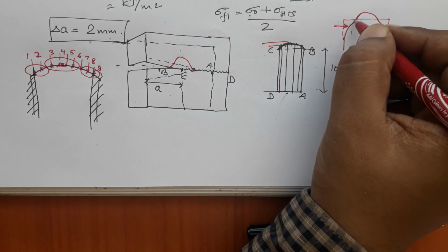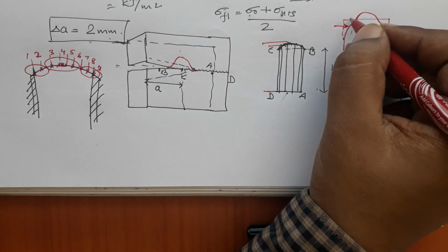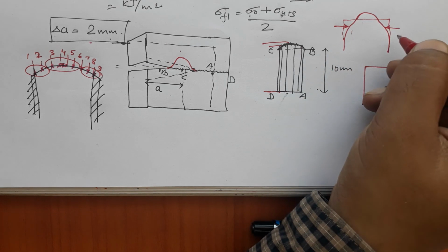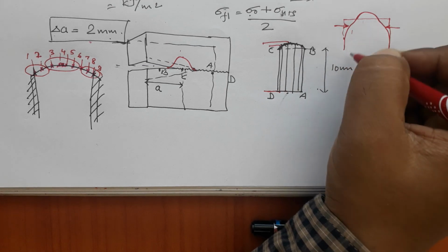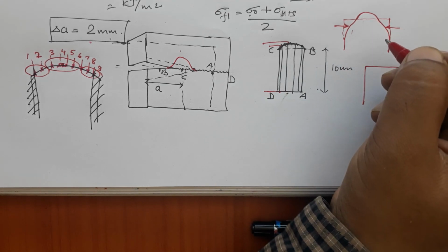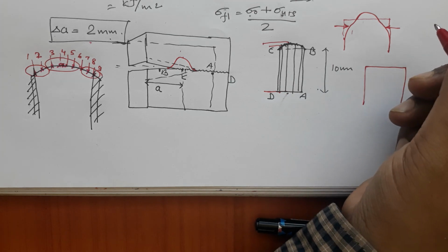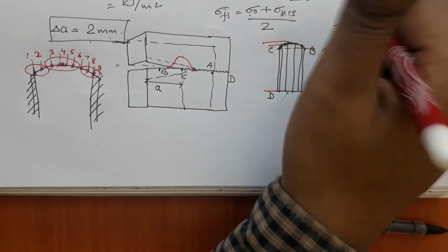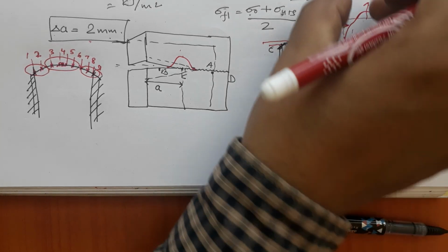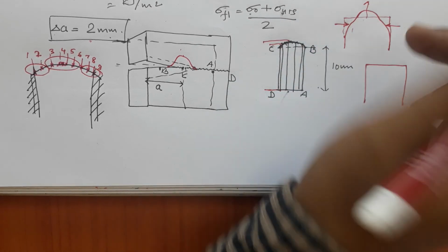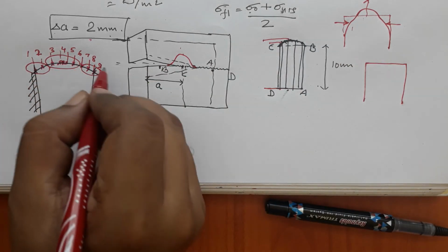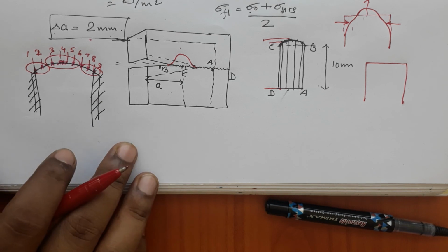So, what has happened is the material has sunk in from the sides. Why has that happened? Because the surface is relatively free in comparison to the center. The center is not getting material easily from all the sides, but the surface is getting the material from this side, from that side. It's like jumping on the bed. When you jump on the bed, the surface sinks, right. Similar to that, you are pulling this part in the top direction, and the material is flowing in from the sides, and that is why you have this kind of shape, okay. And that is why the crack tip has this kind of structure.